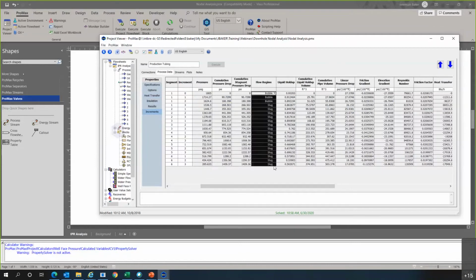And we're definitely going to cycle back to the flow regime to see how that plays a role in our production performance. But a flow regime is based off of obviously the amounts of liquid and gas in the pipeline, but also the superficial velocities of those. The velocities of those will play a role in the flow regime.